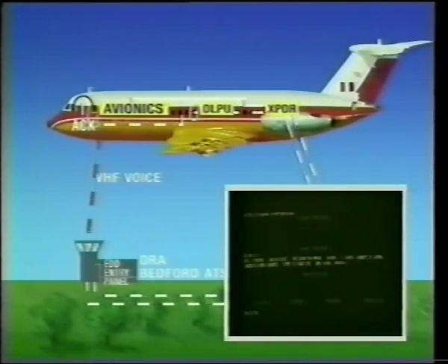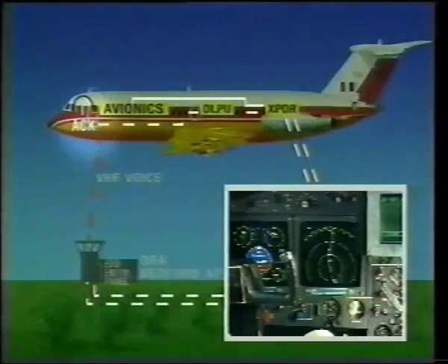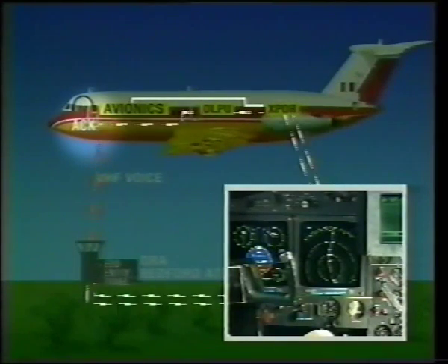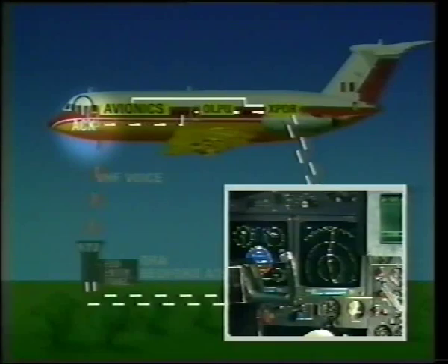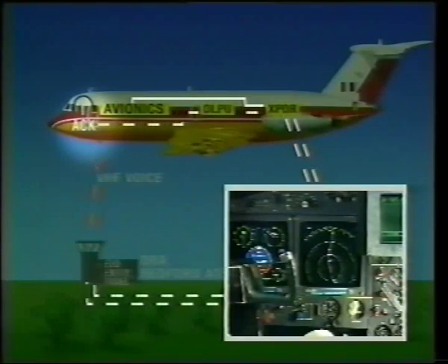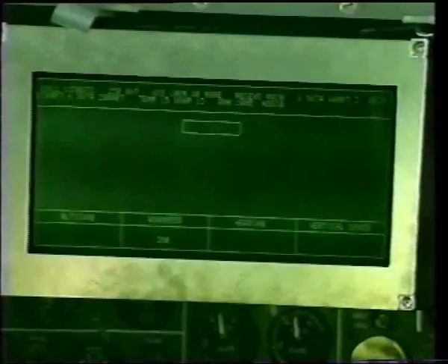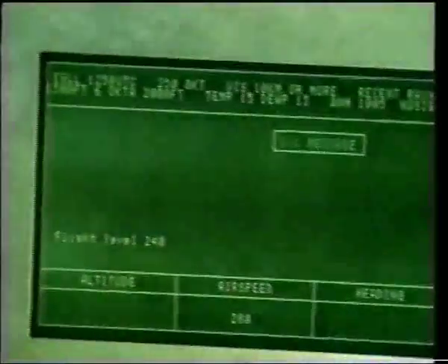In addition to the flight deck instrumentation, the conventional map display indicating the aircraft's route also contains an alert indicator informing the pilot of an uplinked ATC instruction. The data link information for Scenario 2 is displayed on an experimental LCD panel mounted in the center of the cockpit, below the autopilot, where all ATC and VOLMET instructions are displayed. In the center of the screen, there is also a flashing alert each time a new instruction arrives, the latest ATC instruction appearing in the central part of the screen.